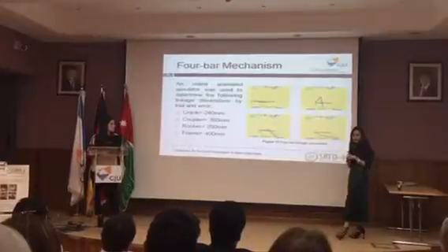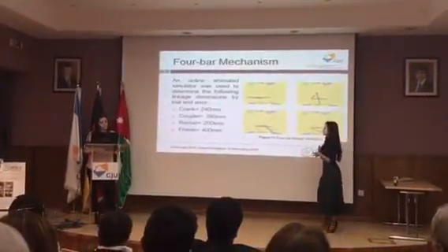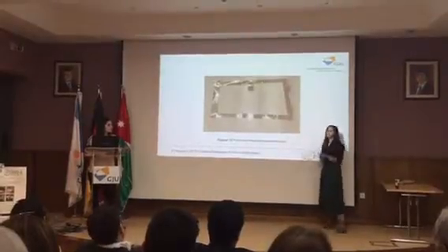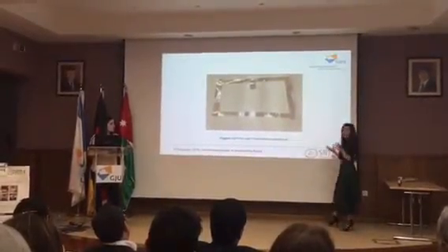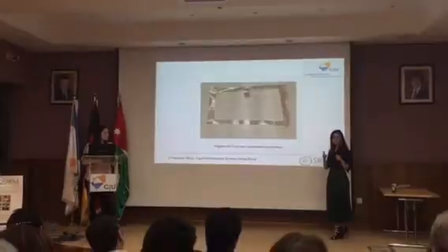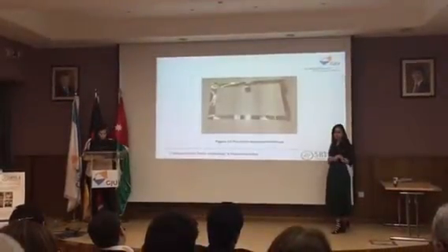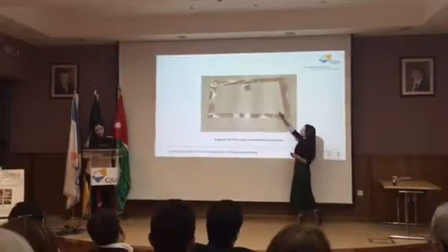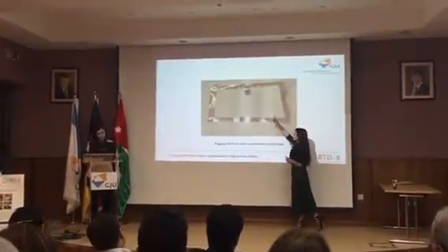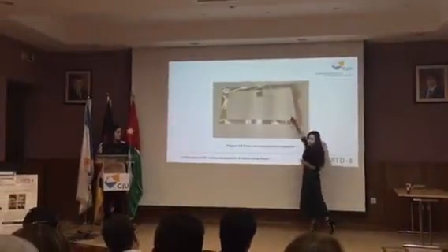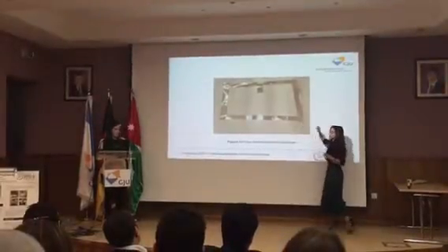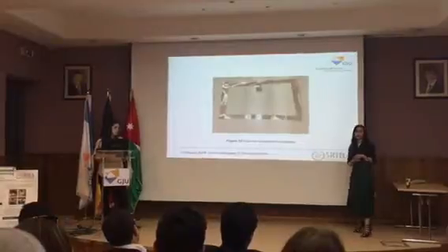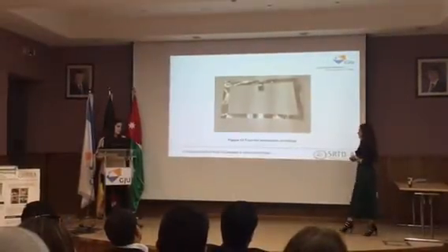To further justify whether our dimensions were going to give us a correct trajectory, we built an early prototype. Here you can see we brought cardboard paper and cut it to the dimensions that we obtained previously in the animated simulator, and then we attached a little pencil onto the coupler, and we drew the trajectory obtained using these dimensions. And we were very successful in obtaining the desired trajectory.